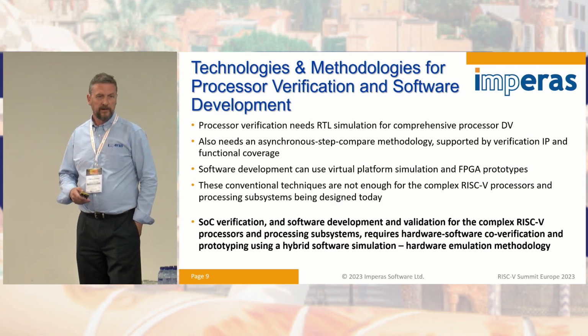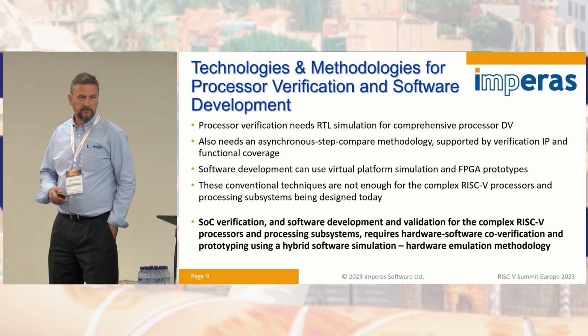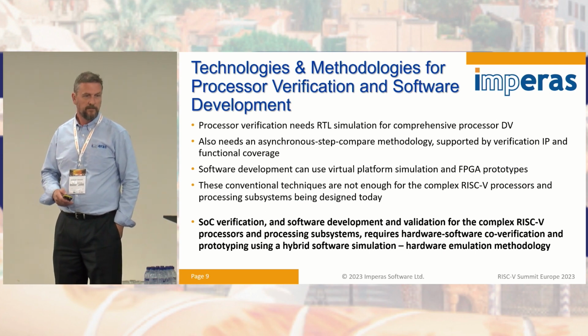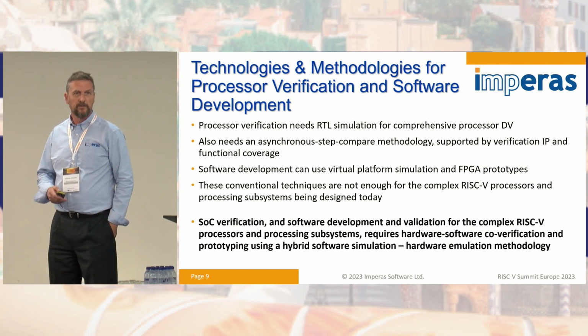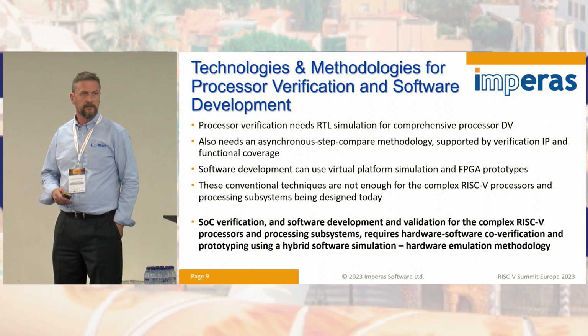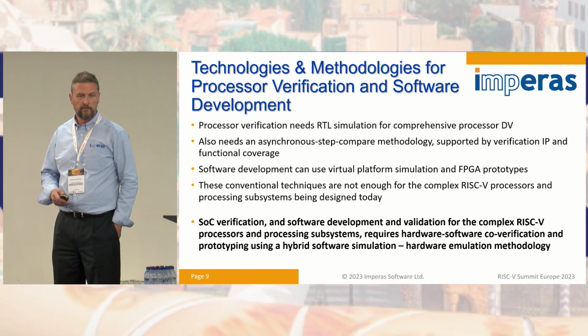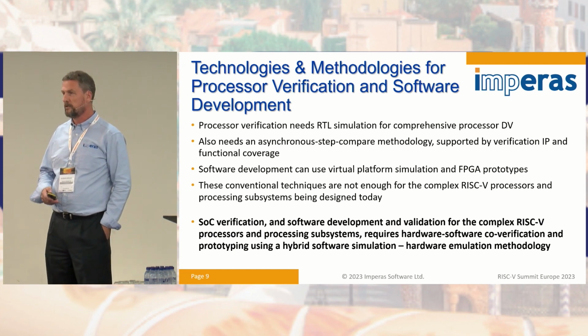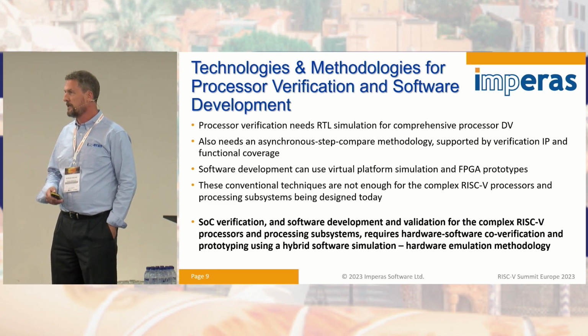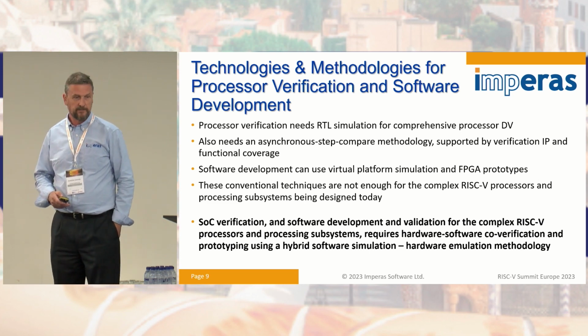Currently, to verify our processor RTL, we need to run RTL simulations. We also need some form of step and compare to be able to check that the execution of the RTL matches the specification. And we need to have verification IP and also functional coverage to make sure that we're actually executing and testing everything that we think we are.